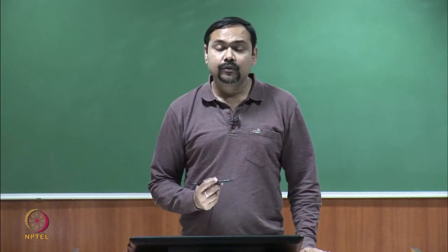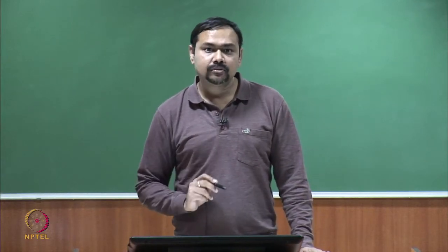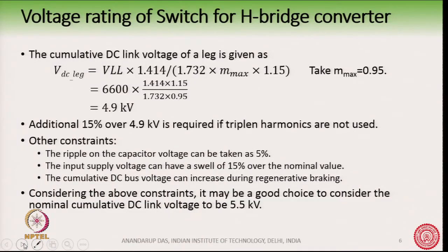So, when you choose the IGBT, you should look into its I square T rating. Now, once we have decided on the current rating of the switches, then we look at the voltage rating of the switches.